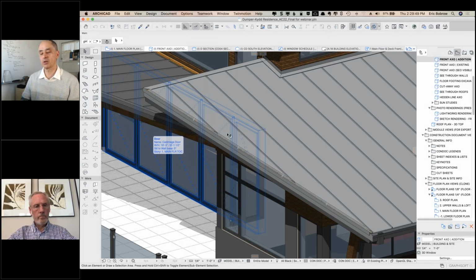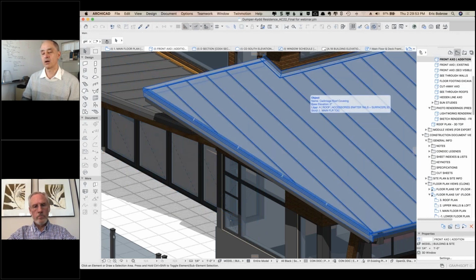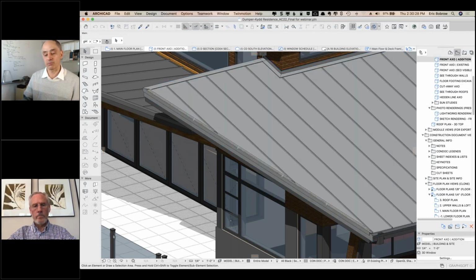In this particular case, the coverings one, we'll use a technology built into ArchiCAD where you draw a basic shape like a roof, and then you say, please cover it with something. And the rules for the covering are flexible, and you can have parts of the wall with wainscoting or with brick or things added on. And of course, the roof's not only standing seam, but beautifully detailed tile and other options. And then if you change the roof shape, it actually updates, so it's associated. So there is a cost, but it does work nicely.